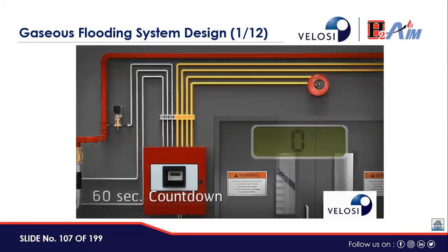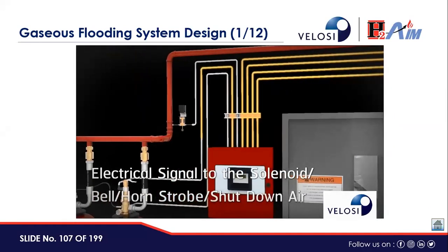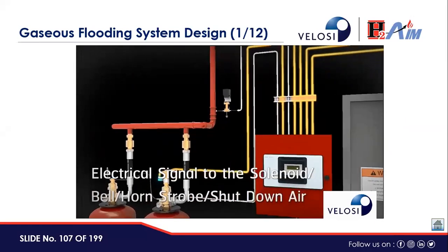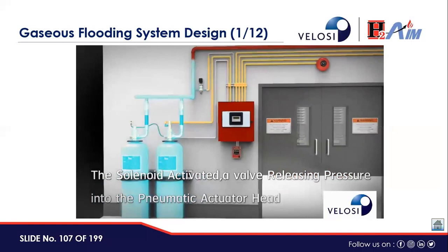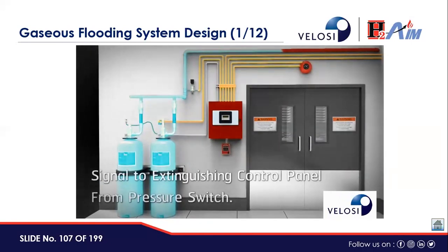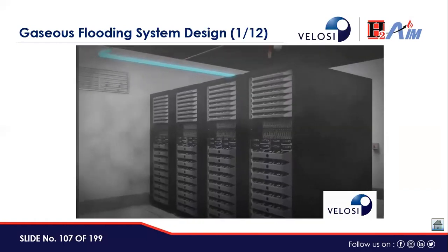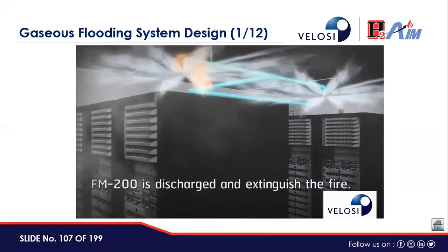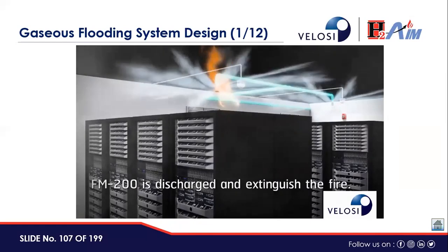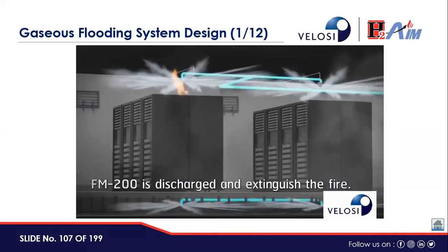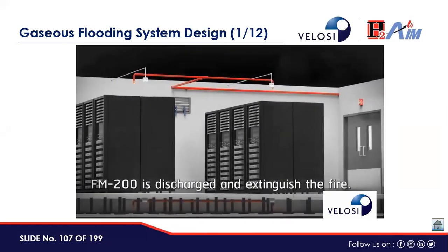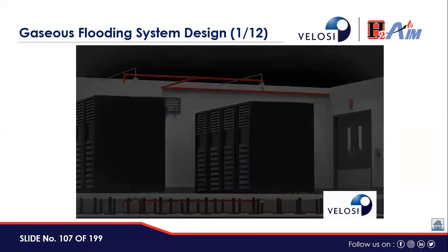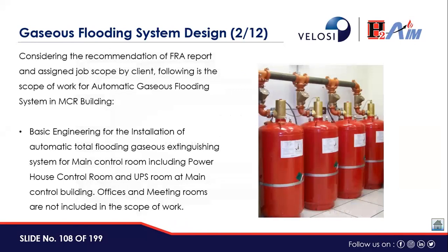If not, then after 60 seconds, it will send the electrical signal to the solenoid and it will activate a valve releasing pressure. Then FM200 is discharged and extinguishes the fire. So in this way, the automatic activation of FM200 is carried out. So now,